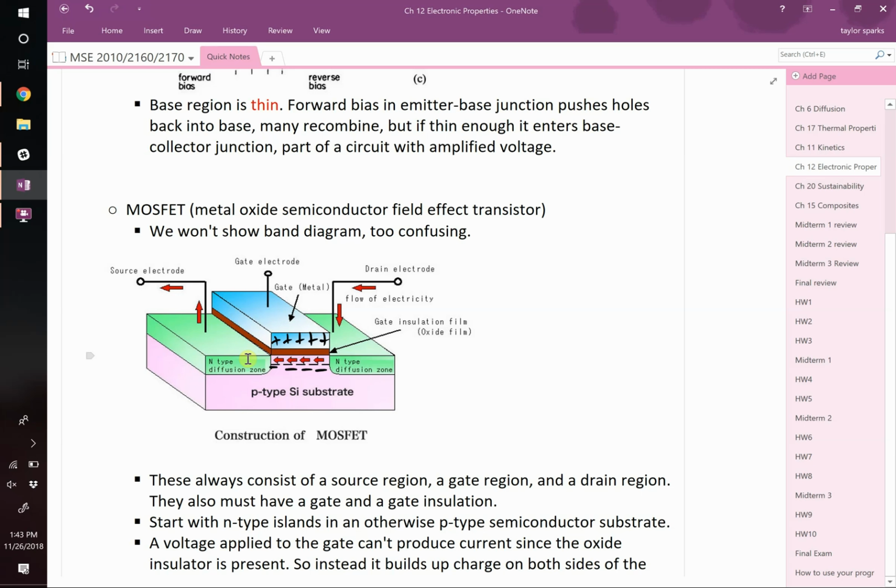Now, it gets to a point where if you have a voltage across that thing and the distance gets really small, those of you that have taken quantum physics have learned about tunneling. When there's an energy barrier, which this technically does represent, but you get thinner and thinner, you get a quantum mechanical phenomenon called tunneling, where it shouldn't actually be allowed to trespass that border and go across it, but it does anyways. And we're getting there. Our transistors are so small that tunneling current, this leakage current, becomes non-trivial, so we can't go any smaller. So what will you guys do?